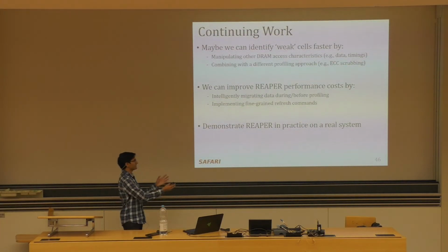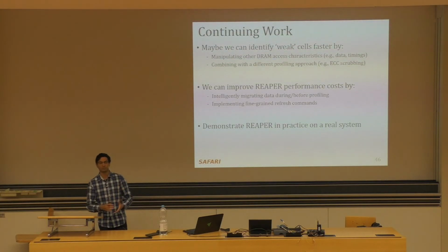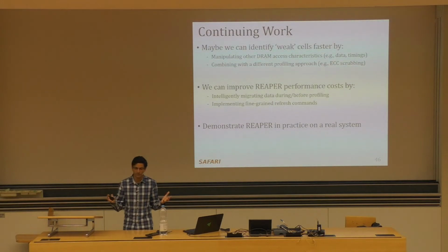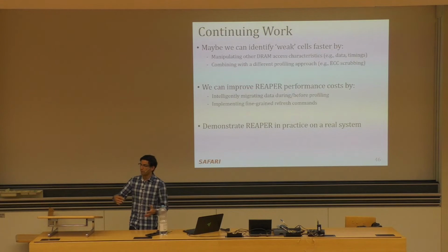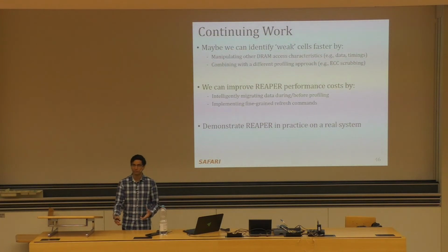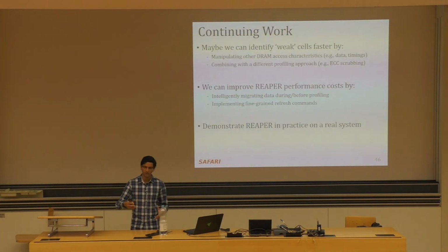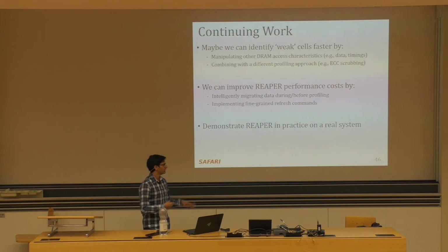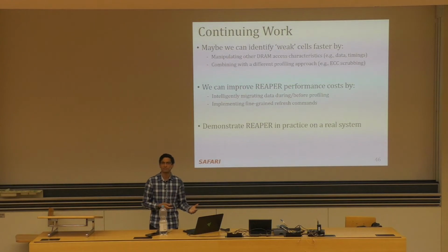And especially at the system level here, right? So we're going to require some system support. Either this firmware that executes, it could be as simple as a state machine in the memory controller, in which case you just tell it to go. Or it could be something more complicated, right? We could have an operating system thread that's in charge of this profiling, and its kernel thread spins up, does some profiling, and then spins down when it needs to. There's lots of approaches, and so implementing on a real system has a different set of challenges than just simulating it.